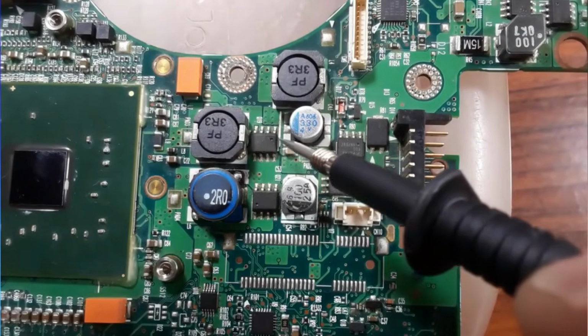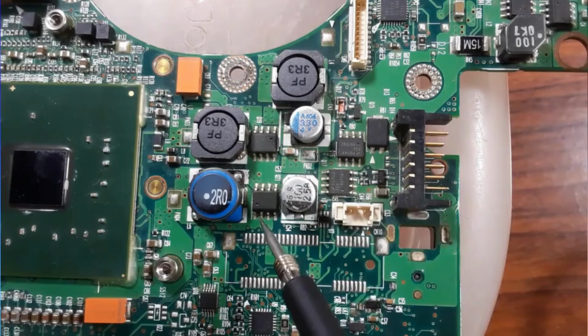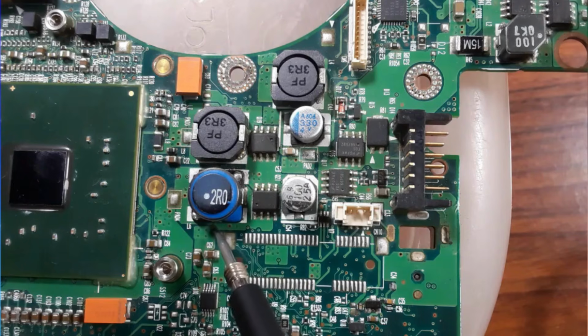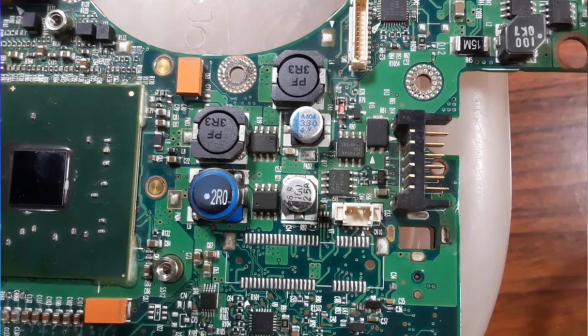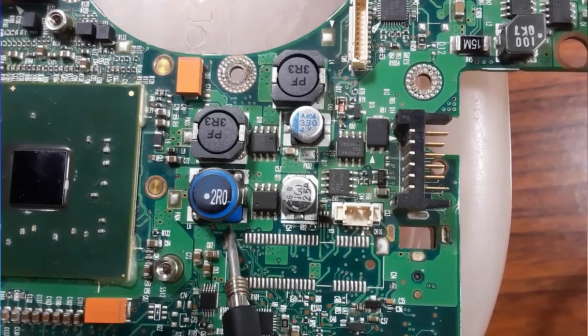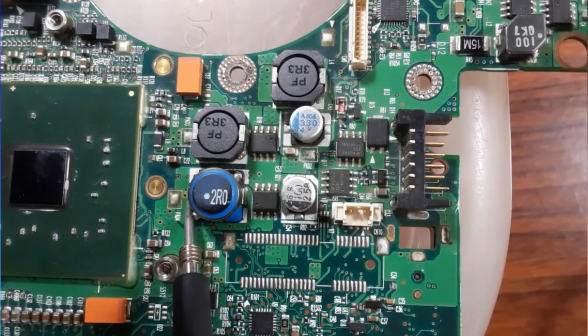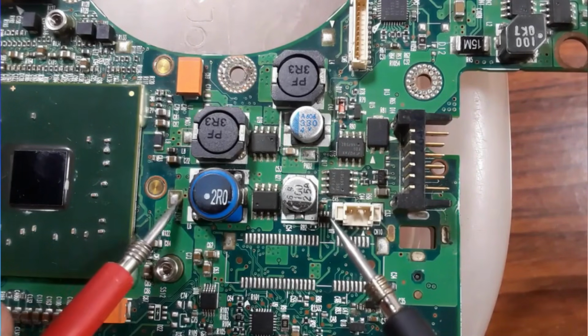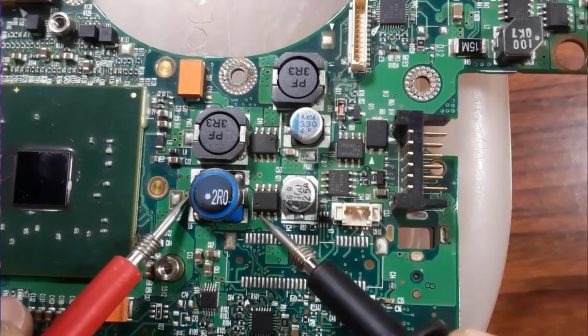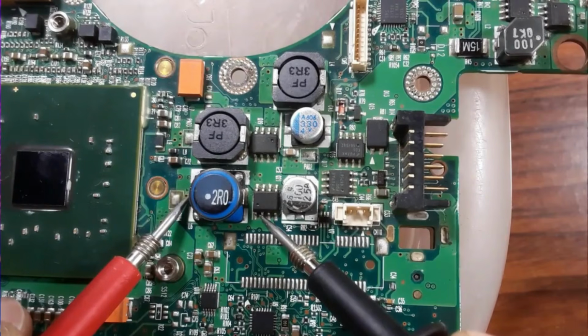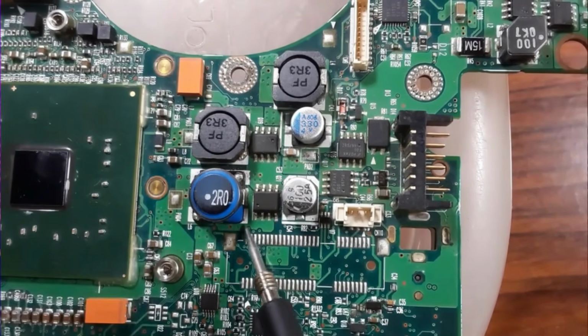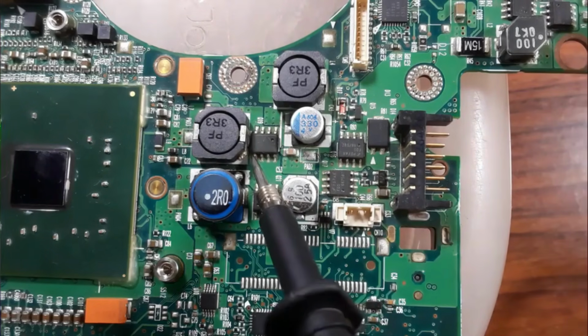And then here, if you look here, you will find that the source of this MOSFET, if we follow this path, as you can see, is connected. Just here we have this path, follow this path, it goes to here. So this coil should be connected to the source, as you can see. Why? Because we have the same path here. Okay, so let's check for this, for example.